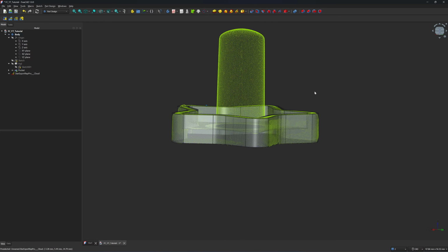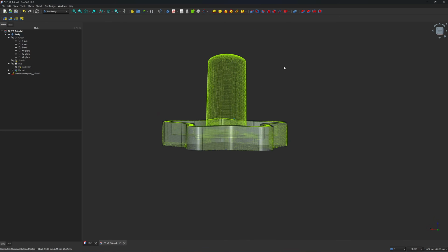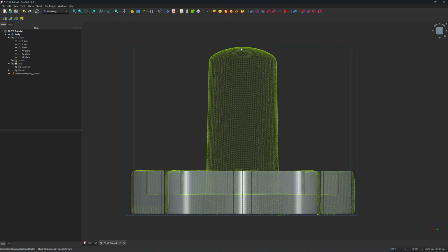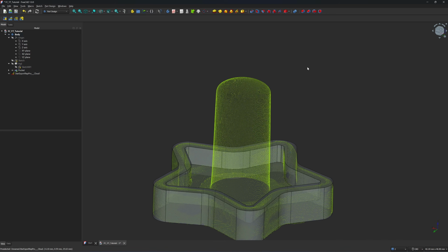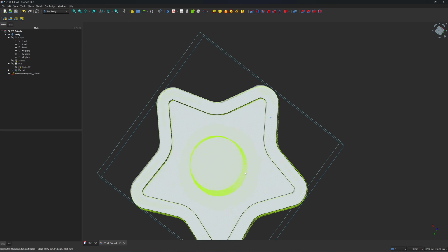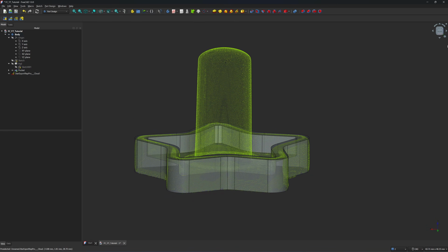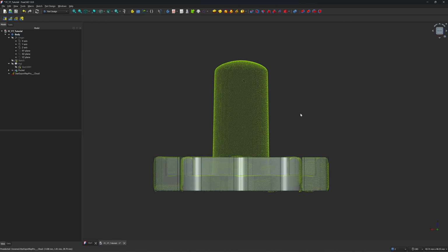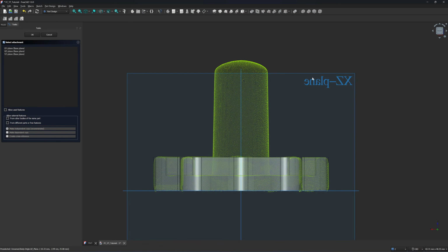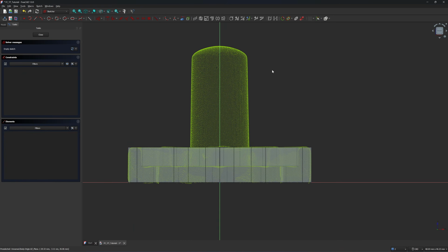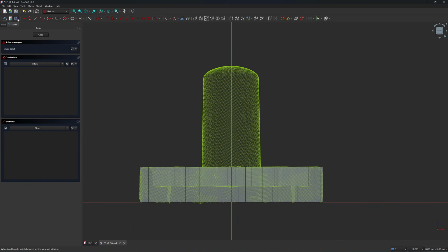Okay, next I'm going to create this shaft here. This shaft, if you look here from the side, is tapered and round, and the top is round with a 2 radius, first radius and the second radius. So I'm going to make a sketch and revolve it, because this cylinder is in the center of the origin point, so it will be easy to do. So I'm going to create a new sketch on the XZ plane here, right?